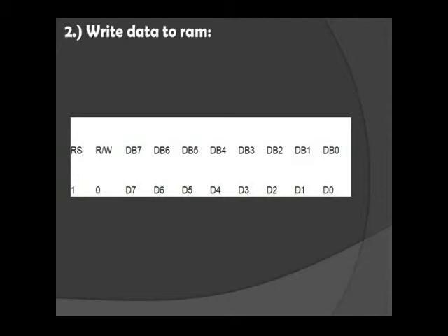Write data to RAM. Write binary 8-bit data to DDRAM or CGRAM. The selection of CGRAM or DDRAM is set by the previous address set instruction, DDRAM address set or CGRAM address set. The RAM address set instruction can also determine the AC direction to RAM. After the write operation, the address is automatically increased or decreased by 1 according to the entry mode.